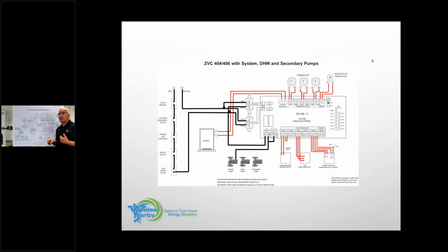So we're bringing power into common. And now I'm taking power out of normally open to my domestic pump, and I'm bringing power out of normally closed to my secondary pump. That's just bringing power in, and then we completed, this is the white wires, we've completed that circuit.